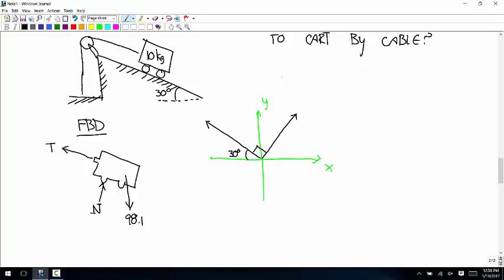So that's going to let us figure out what the unit vectors are representing the vector in the normal force direction and the cable tension direction. So first, to get the unit vector representing that, start at the positive x-axis, counterclockwise to 180, right? So positive 180, backtrack 30, so the angle's 150.